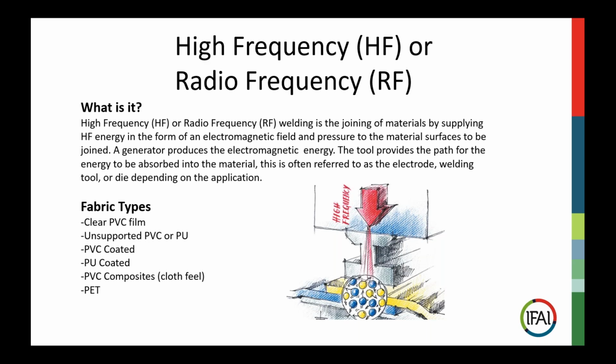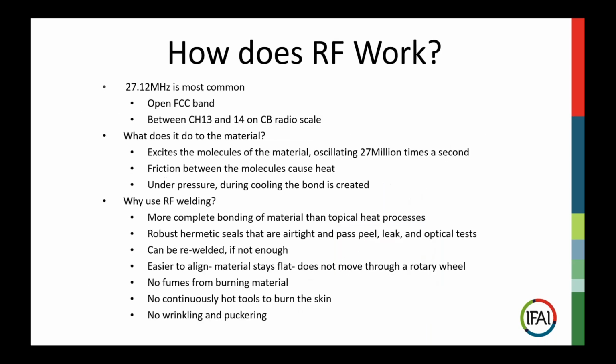Here you see a list of materials that are naturally reactive to RF or HF, and you'll see that I actually did include a PVC composite, which refers to new materials now. There's new technical materials coming out every day, and some, like the Natura from Herculite, are actually very cloth-like in the touch and the hand, and they're actually used in place of an acrylic, for example. They are completely RF weldable, so don't be fooled that you have to see some kind of shiny material to do RF welding.